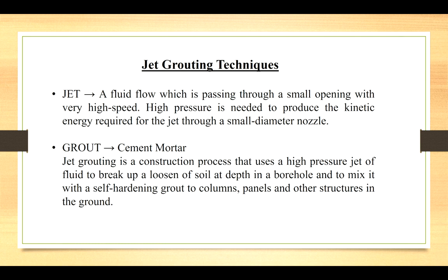The jet grouting technique is generally categorized under two different names, jet and grout. The jet is a fluid flow which passes through a small opening with a very high speed. High pressure is needed to produce the kinetic energy required for the jet through a small diameter nozzle. Grout also has many different materials, but the common one is cement mortar. Jet grouting is a construction process that uses a high pressure fluid to break up a portion of soil at depth in a borehole and to mix it with a self-hardening grout to form columns, panels, and other structures in the ground.